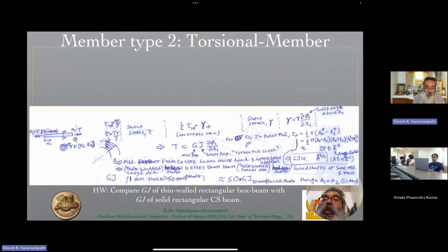And we denoted the force by a single arrow. The moment or torque will be denoted by a double arrowhead, as you see over here, right? Which follows, of course, the right-handed thumb rule, which means that if this is the direction in which the double arrow is, that means the torque is essentially going in the direction of the other four fingers. So the thumb indicates the direction of the vector, and the other four fingers indicate the direction of the actual moment that is involved.